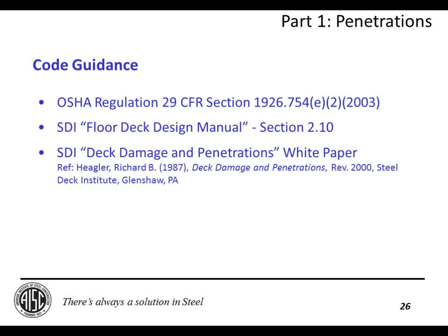There's a good deal of guidance out there regarding penetrations through the slab. There's some more practical guidance as well as some ideas for how to reinforce the slab. OSHA Regulation 29 CFR Section 1926.754(e)(2) 2003 discusses it, as does SDI's Floor Deck Design Manual, and SDI wrote a white paper in '87. It was updated in 2000 that discusses some options for reinforcing around penetrations. So we'll take a look at each of these in turn.